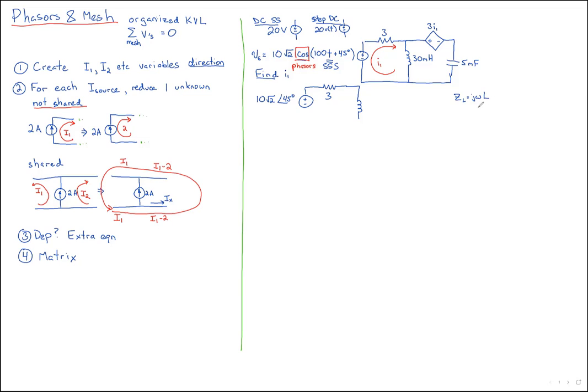What's our omega? Omega is 100. That's right. Times the 30 millihenries. So finishing that, the number part is 3,000, and 1 times a milli is a milli, and that's all j. What's the simpler way, Grant, of writing 3,000 millis? Just j3. That's it.